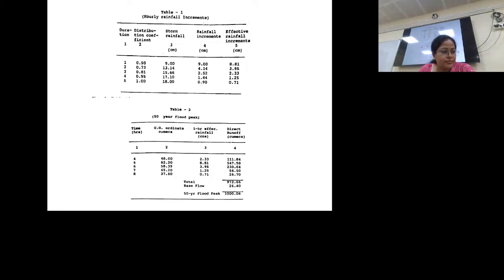Basically, when we learn hydrology in college, what we see is the length and the shape, basically fan shape or fern shape. Those were the two shapes we always design, because that depends on your arrival time. So for length, we are more interested in the longest flow path, because that will be the longest time it will take, because to reach the peak all streams should contribute. So the longest flow path is important, and slope, because slope will determine what the velocities are. So it's logical how these parameters have been derived and what their use is.